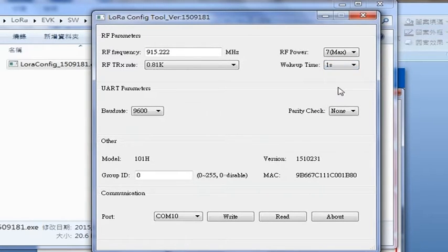For the RF setting with 1 second for power saving mode, it wakes up in several 10 ms intervals to check for a wake code every 1 second, in order to ensure the TX commands are received. The above commands for RF frequency, RF TRX rate, and wake up time must be set equivalently on both TX and RX.